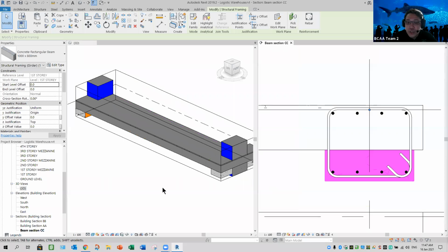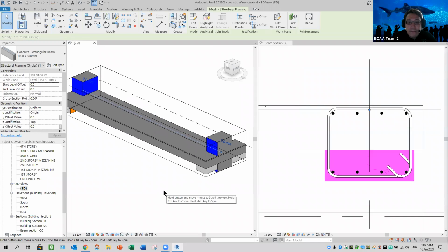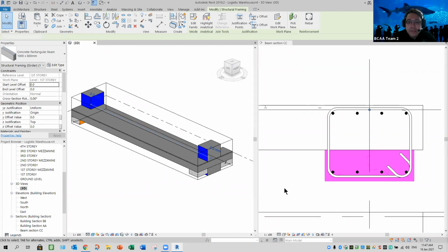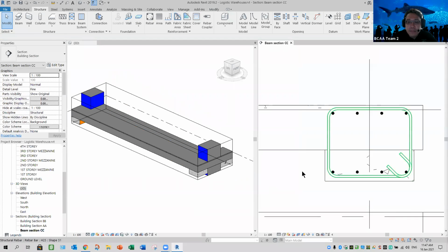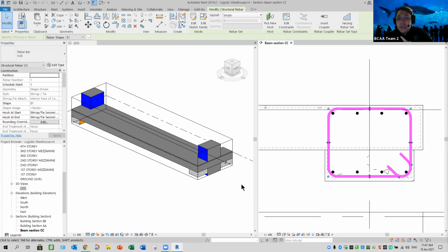Okay, here comes the magic. Why do I say magic? Look carefully. I select the stirrup. That's one thing. But you notice it doesn't show in the 3D. In your layout, I don't want to have a single, meaning only one. I like to have maybe a fixed number, for instance. By default, they show me 3, fine. But here, at the section view or in the 3D, I like to see the 3 stirrups that are there. But you notice that it doesn't apply here.